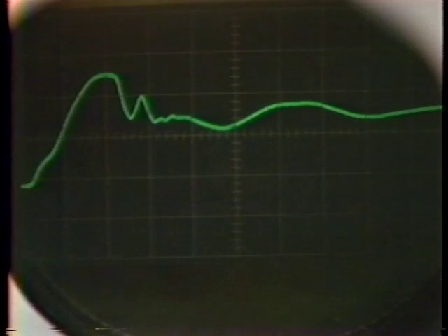Again, the same thing, a nonlinear response because we have no way of slowing down the motor. The power amplifier that I have can only accelerate the motor. The best it can do is stop accelerating it, reduce the motor voltage, and let the friction of the system slow it down. So it's nonlinear. It turns on better than it turns off. We're looking only at the positive transition here, but when we come around the corner, when the motor has to slow down to recover from an overshoot, there's a nonlinearity there.